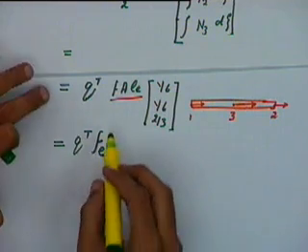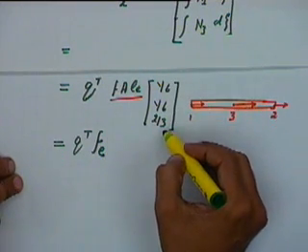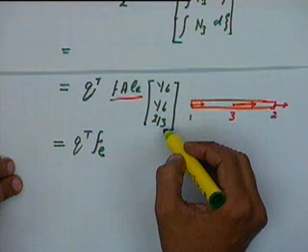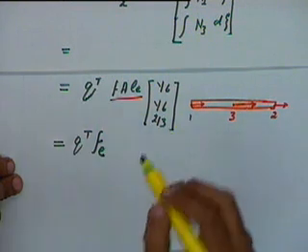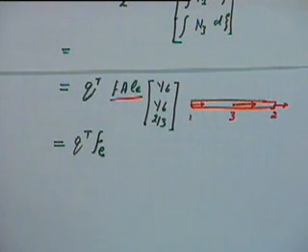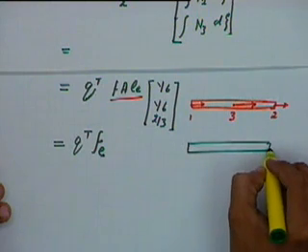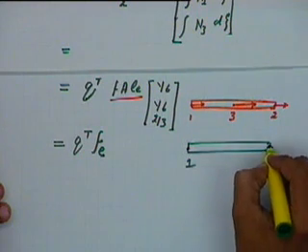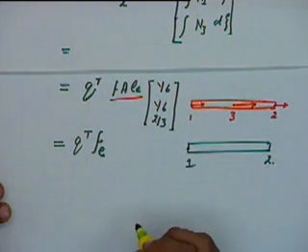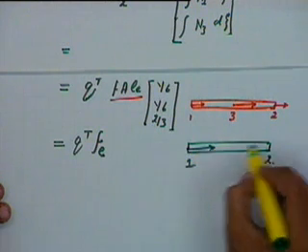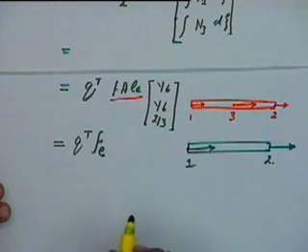Okay, so total body forces acting on the element are divided into the three nodes in this proportion. In the earlier case, when you are taking a linear element, we had two nodes, one here and one at the other end, and the total body force was divided equally in the two nodes.